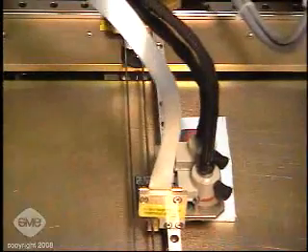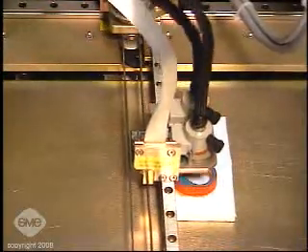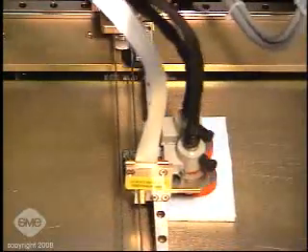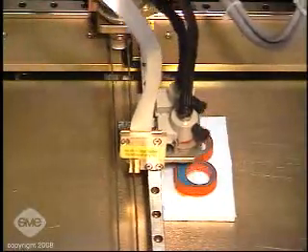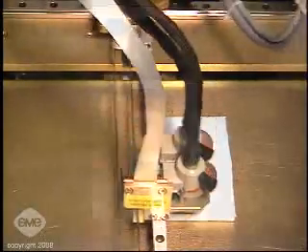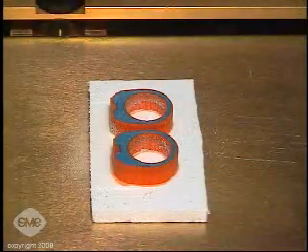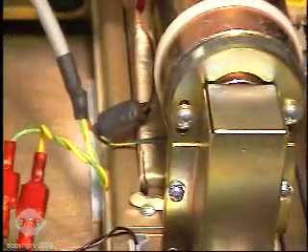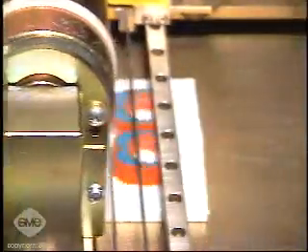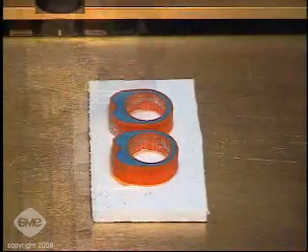The 612 can produce models up to 12 by 6 by 6 inches. Layer thickness can be as thin as 5/10,000ths of an inch. To ensure precise layer thickness, a milling operation is performed between layer buildup. This is carried out until model completion.